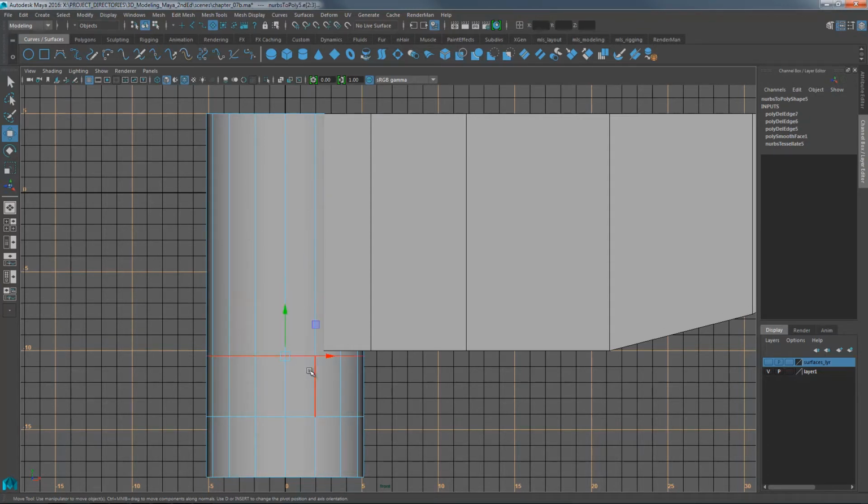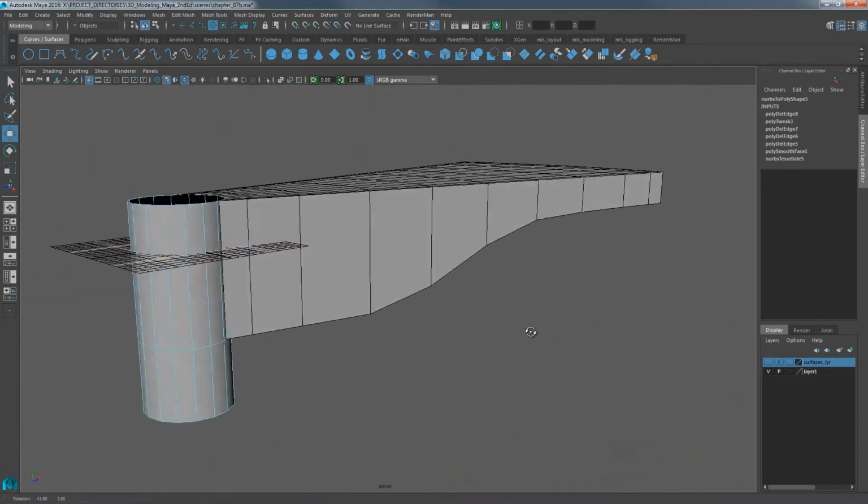Then let's set this one here to be at an absolute value of -10, like we did the vertices on the steel part, on the front steel part. So -10. And then we can remove this row of vertices there. So that really simplifies that problem as well.